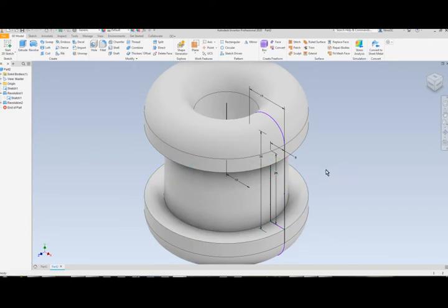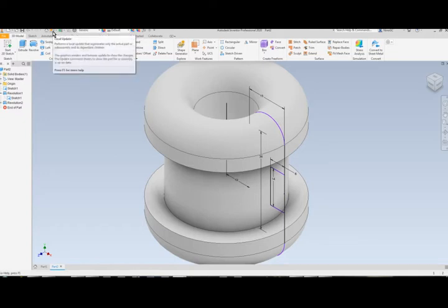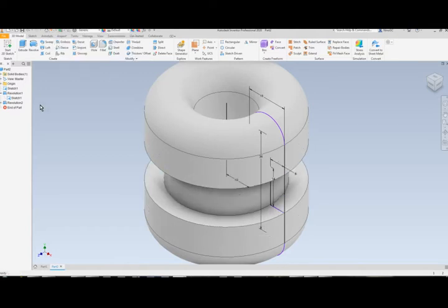Now, all of the dimensions are still exposed. This is very convenient because what this will allow me to do is make a few changes. For example, let's say 26. I don't like 26. I actually want 14. So I'm going to type in 14. Now, nothing's happened to it. The reason being is that I have to go upstairs to my update, which is right here, to do a local update. So when I hit that update, it adjusts.